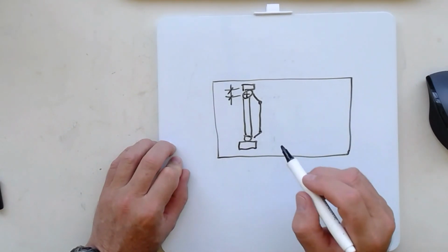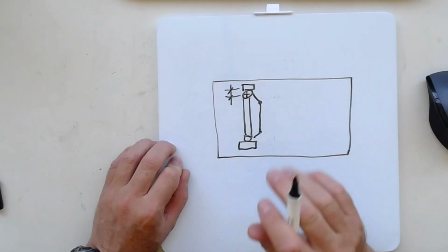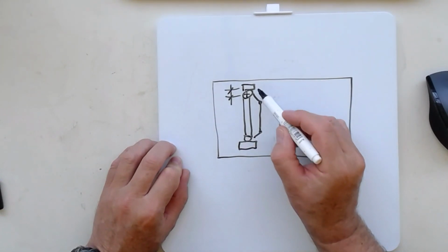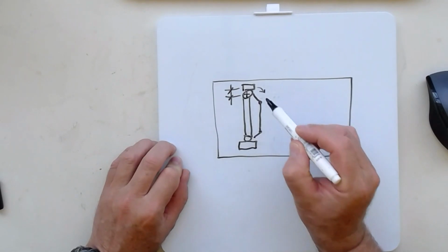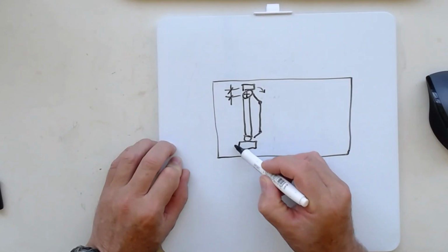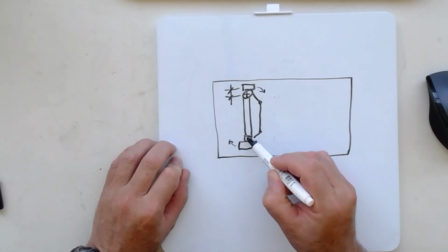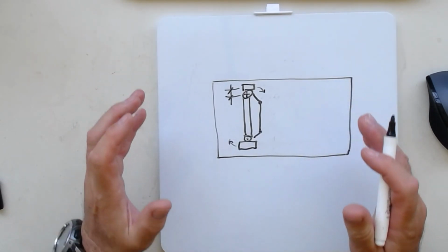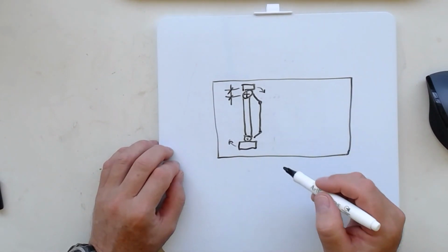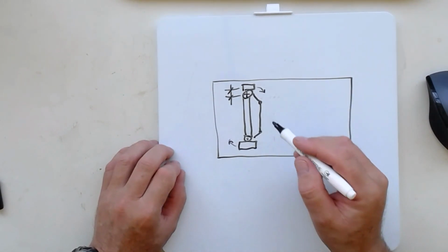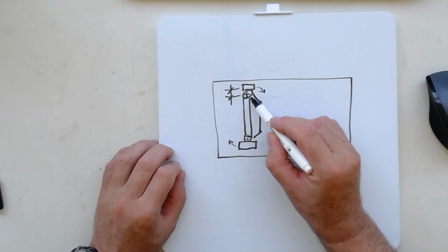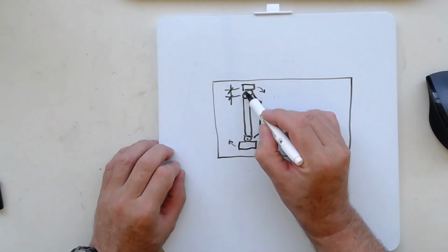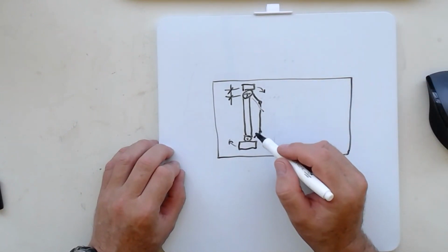So if that vehicle is just stationary there and you choose to steer it, what will happen is that this tyre will move like that, this tyre will move like that. They'll go around the kingpins, but they'll also move the vehicle because the contact patch on the ground has changed. You're generating a torque around this pin in order to steer the vehicle. That's probably obvious.